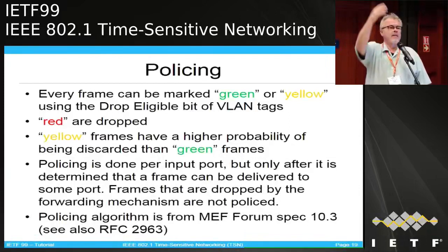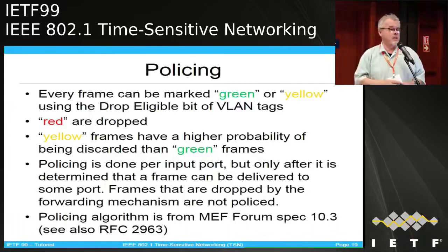So we can insist that the brake sensor not only transmit only the brake sensor packets, but it only transmits them at these times when it's supposed to, and that it only transmits the one. Okay? Now, a brake sensor that runs off at the mouth and starts transmitting continuously can't screw up the rest of the car. Various ways to deal with that.